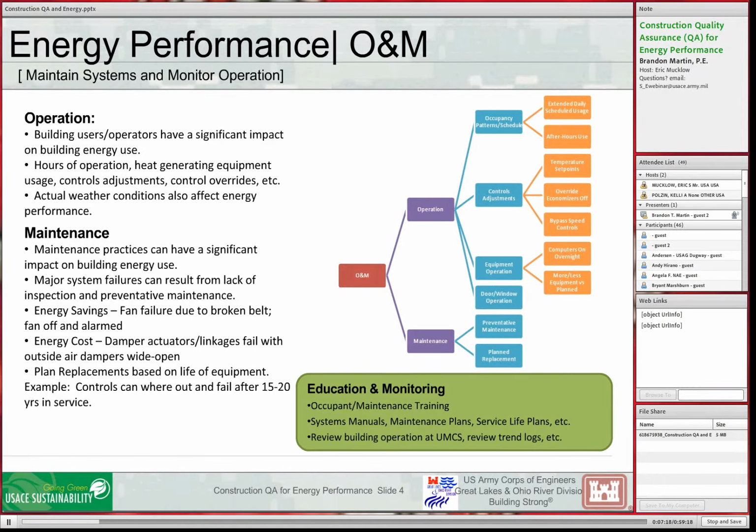After we turn the building over, that's when we find out if the design is worth anything by looking at trend logs, making sure that everything's running the way it's supposed to under the load it was actually designed to handle. We don't really know at the end of construction whether the design is going to function. The only test of the design comes when the building's already occupied. So it's a follow-up measure we need to take.